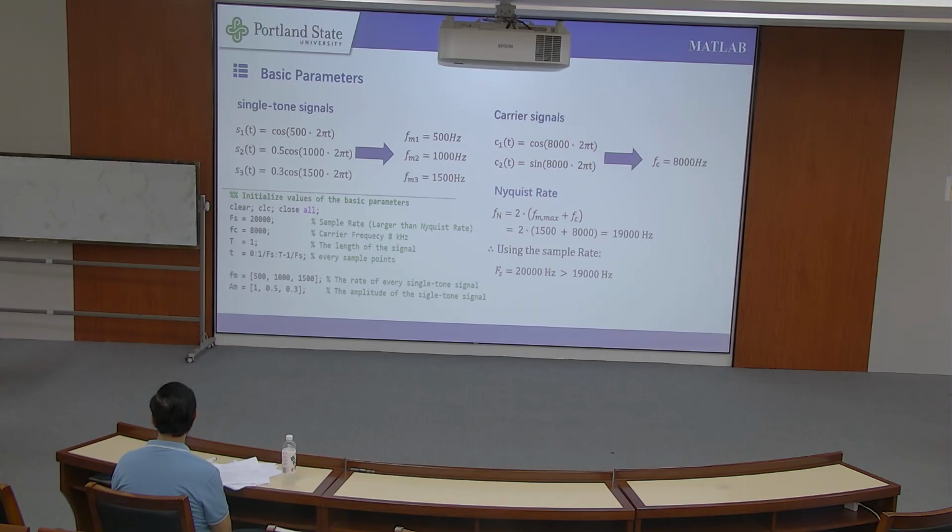In this step, we will take the multi-tone baseband signal f(t) that we defined in the previous slide. The first one is made with 500 hertz, the second one with 1000 hertz, and the third one with 1500 hertz. In our code, we will use the built-in Hilbert function to get our 90 degree phase shifted signal with just one line of code.